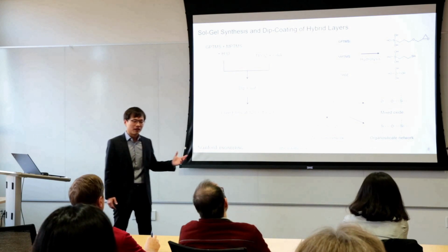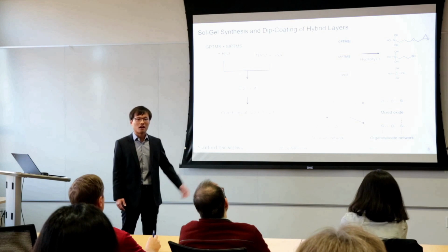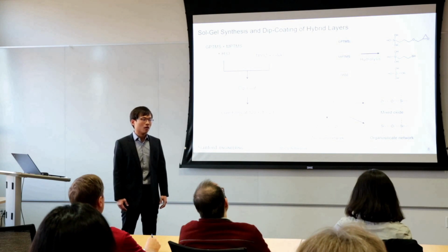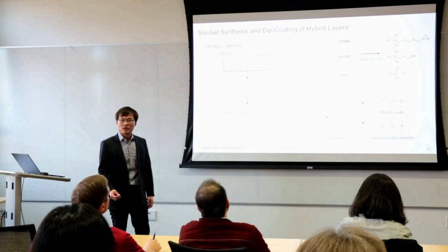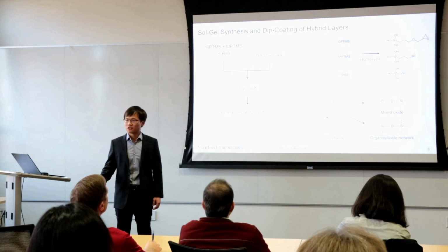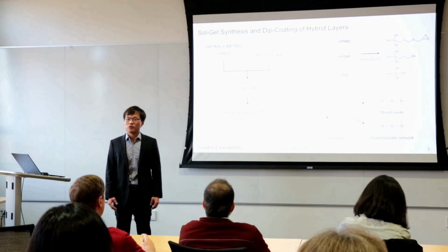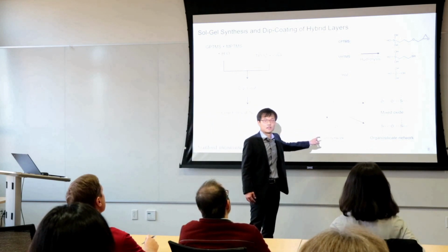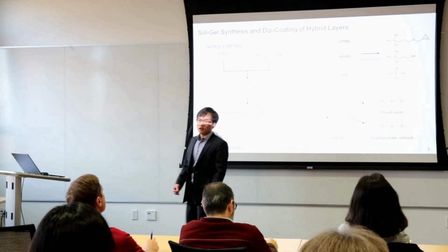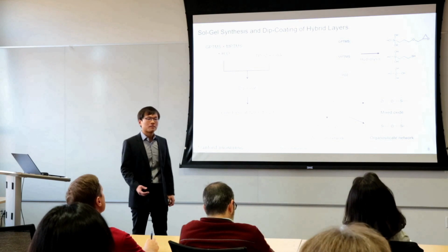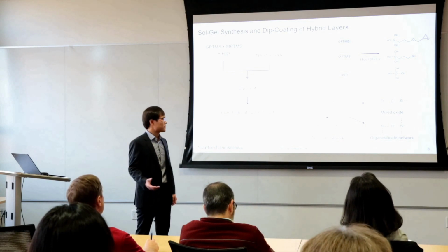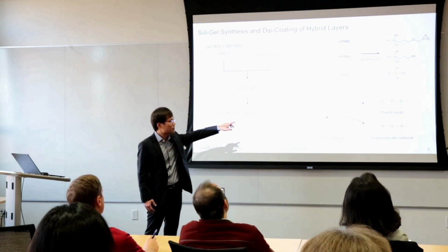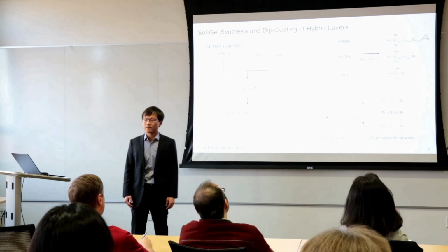And during this time, a series of hydrolysis and condensation reactions occur, whereby the acid stabilized zirconium species becomes more and more soluble in solution over time and reacts either with other zirconium species to form a zirconium network consisting of zirconium-oxygen-zirconium bonds, or the zirconium can also react with silane molecules to form the mixed oxide zirconium-oxygen-silicon bonds.